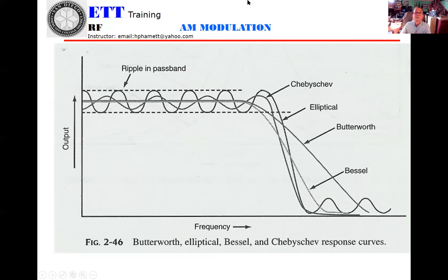Okay, if you're looking at the one with very good cutoff, that means steep right here. Very good cutoff, however, they get a lot of noise. Okay, so for this one, if they ask you, then the good choice will be Butterworth. Okay, the thing is it will be flat during the mid range, and also the cutoff will still be good.